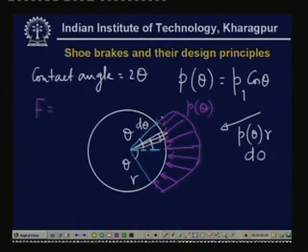Let us take this angle to be not phi but theta. At small angle theta, we have to differentiate between two things. Here is theta 1, and it goes from minus theta to theta, but I have taken a small element delta theta at an angle theta from it. So while taking the integrations, we will have to make sure that the two limits are taken properly. The force per unit length of the drum, that is, if the drum is taken to have unit length, then the net force on this particular area is p theta r d theta.